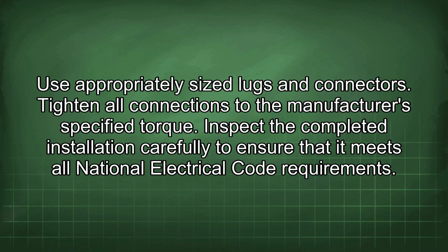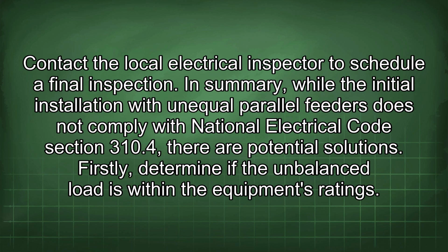Tighten all connections to the manufacturer's specified torque. Inspect the completed installation carefully to ensure that it meets all National Electrical Code requirements. Contact the local electrical inspector to schedule a final inspection.